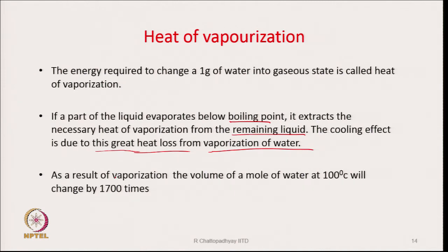As a result of vaporization, the volume of a mole of water at 100 degree centigrade will change by 1700 times. This kind of information will be important for us, because there may be situations when the water may vaporize, and suddenly a lot of volume will be required to tackle this vapor, especially when we are thinking of designing firefighters' clothing, where the temperature outside may be very high.